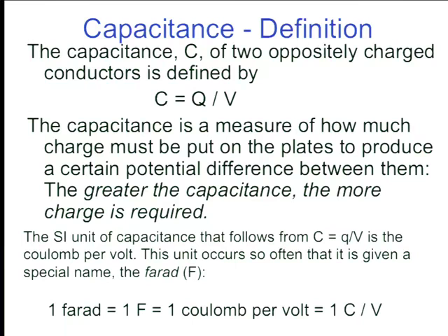The quantity of charge on a capacitor is the capacity, that's a geometrical factor, as you'll see. It just depends on geometry, times the voltage you put on. So the voltage is analogous to the height that you put in, and the capacity is analogous to the area of the tank. So that's my feeling for what capacity is. And actually, this analogy will work very well. You can derive all the formulas for capacity based on a tank of water of a certain height, or voltage, and a certain capacity for the area.